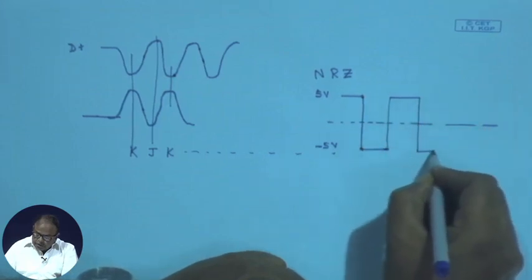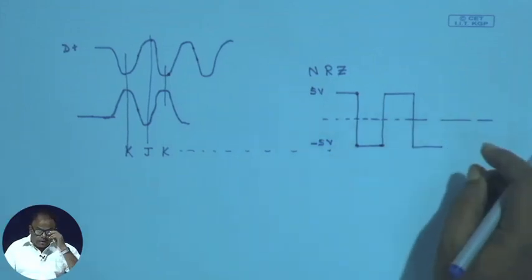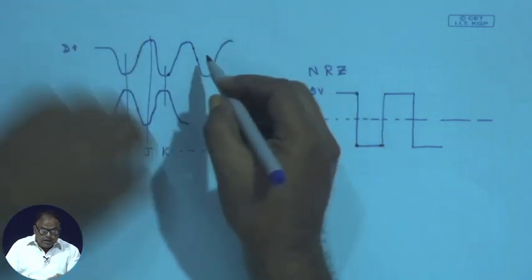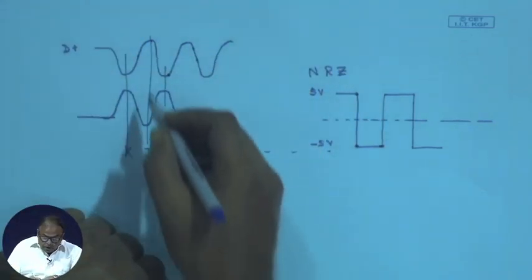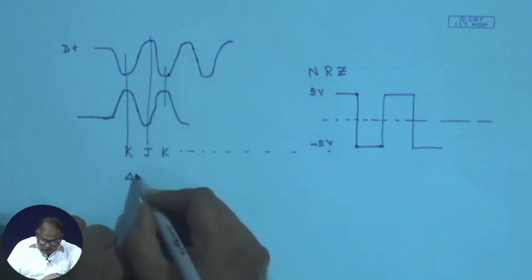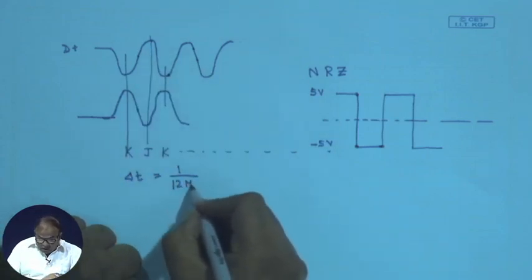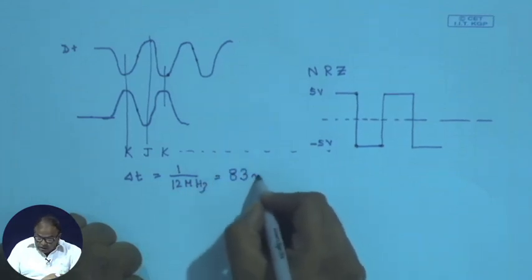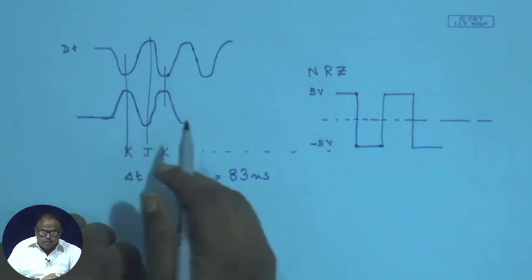And this you might already know when you have learnt about Manchester decoding and all those things. Now, USB, say for example, between each of these data there is, depending on the frequency, say I have got 12 megahertz in our case, that means around 83 nanosecond is the difference between these 2 points.